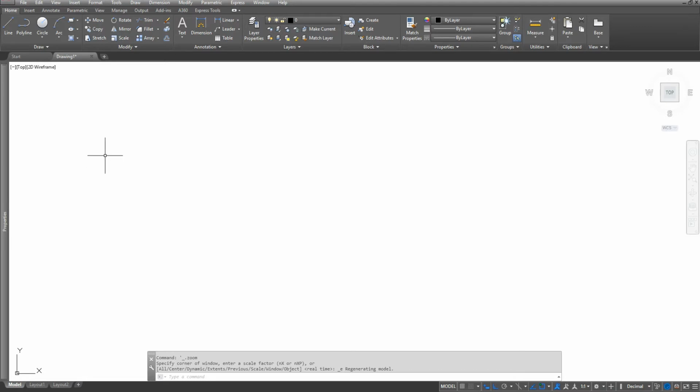Here's an example using one of those methods. When I look at an example like this one, I like to try to decide which way will be the easiest way to approach any math hurdles or anything that I need to do to make this problem as easy as possible. Just by looking at it, I think the easiest method to use on this one is going to be the ortho. So the first thing, remember with the ortho, is that we're going to make sure that ortho mode is turned on. So ortho mode is on.